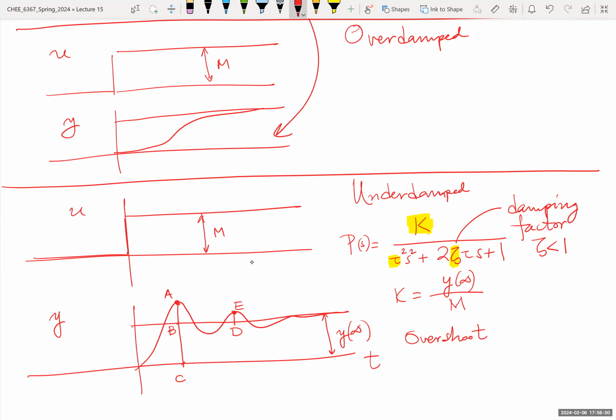The term overshoot is generic. Remember we said when we talked about the Ziegler-Nichols tuning rule, Ziegler-Nichols creates a closed loop that exhibits a little bit of overshoot. What is overshoot? Well, if I have here an input that is a step change and it drives my output eventually to this value, initially the output overshoots a little bit.